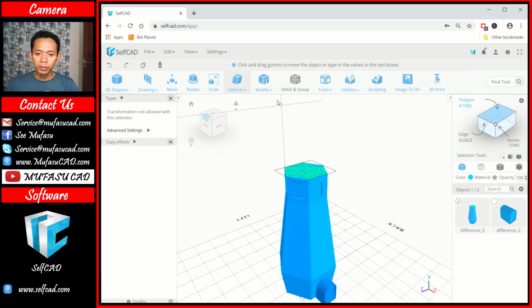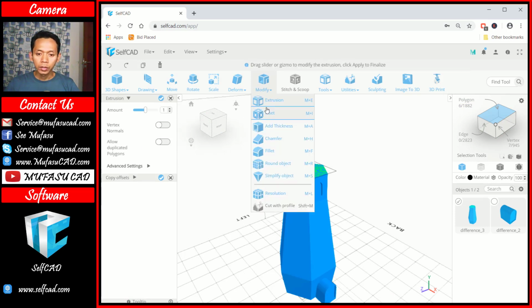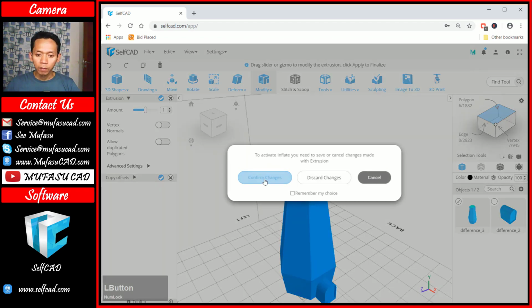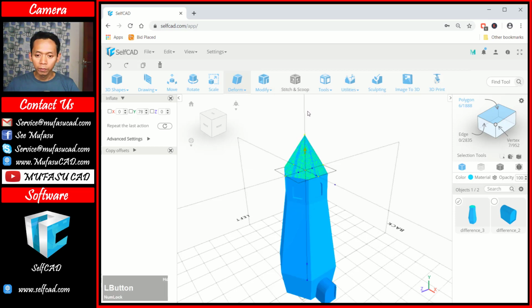We can use the extrude command. Okay, I will use extrusion, and I will extrude it by amount 1. Click OK. Now we can use this command, inflate, to inflate this face. You can click in here and move to the top.